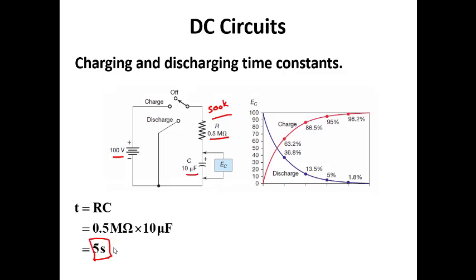When we deal with these circuits, again, we're not going to worry about them in this case, but it takes 5 time constants in order for the capacitor to become fully charged. So this would be 1 time constant, which would be 1 tau, 2 tau, 3 tau, 4 tau, 5 tau. So what we're looking at is this amount of time and how far we're charged. So this would be 5 tau, so that with tau being 5, this would be 25 seconds. So if we hook this up, it would take 25 seconds for the capacitor.